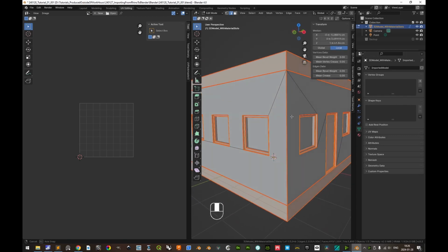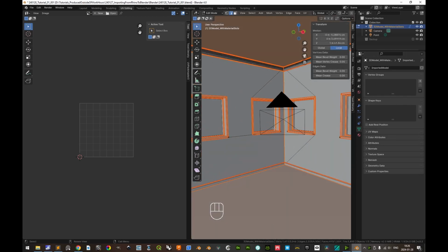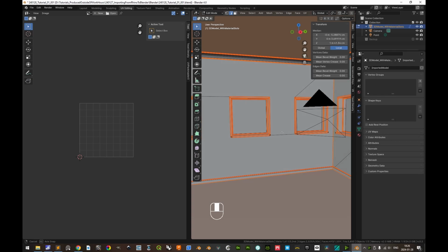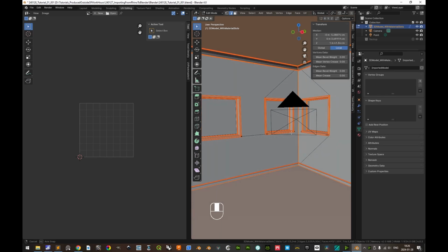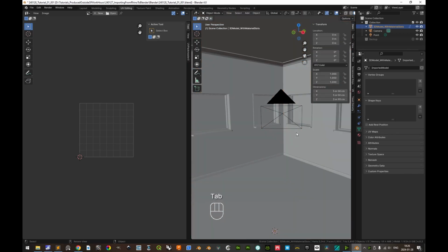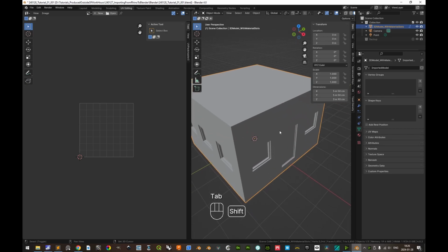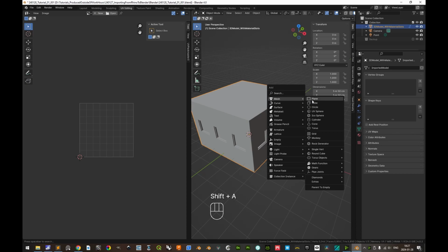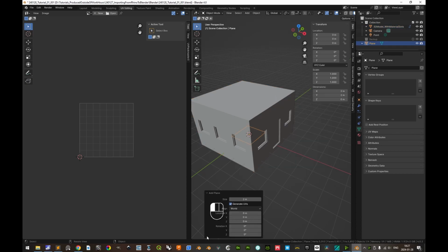For these kind of objects, intended to be textured with real-world scale material textures and not individually painted, the following workflow is what we usually do, but it can be done in many different ways. Let's first press Tab to exit editing mode and enter object mode again. And then we'll do like this. Shift A to add a new object. We'll do a mesh plane. We'll click the small triangular icon here to expand that. And then we make sure that the size is 2 meters. That's a good real world reference. And then we make sure that the generate UVs option here is checked.